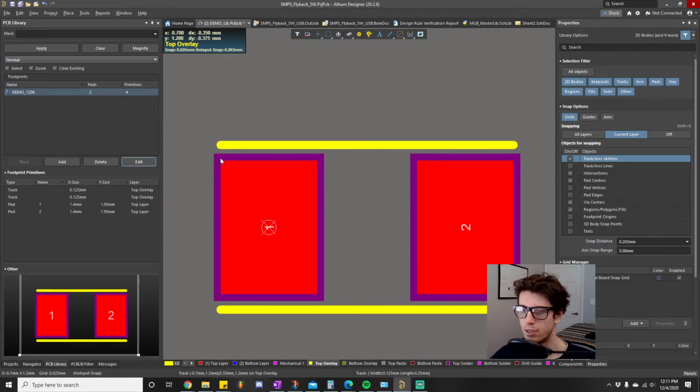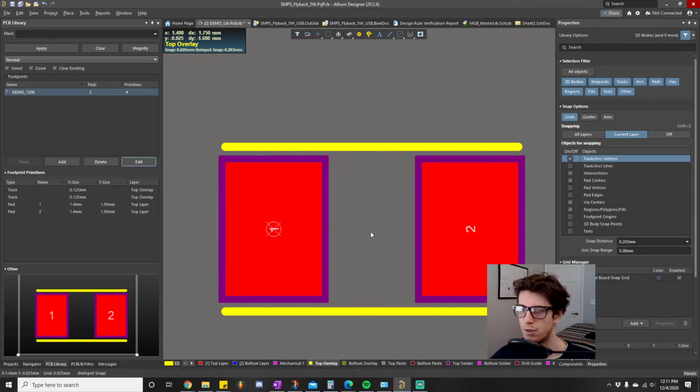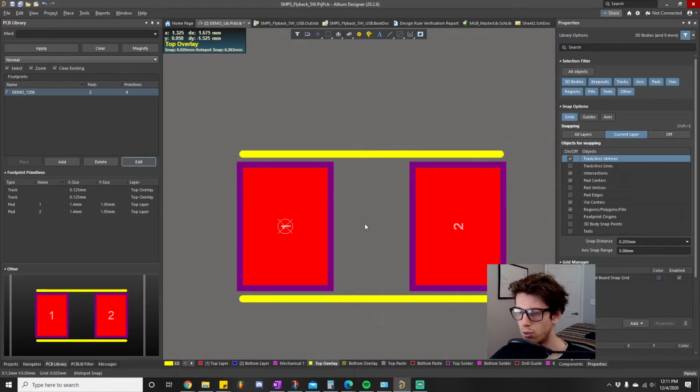So basically what it's saying is whenever the solder mask is generated and they go in to print this little layer, because this is going to be in an ink type, imagine a sheet of paper getting printed out. That's what this is, like writing and artwork. This doesn't really serve a functional purpose per se in terms of the electrical performance of the board, but it still has an aesthetic purpose. But it could cause problems that way, is what I'm saying, and lead to lower yield.